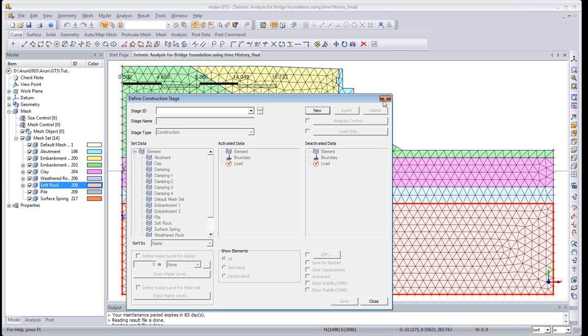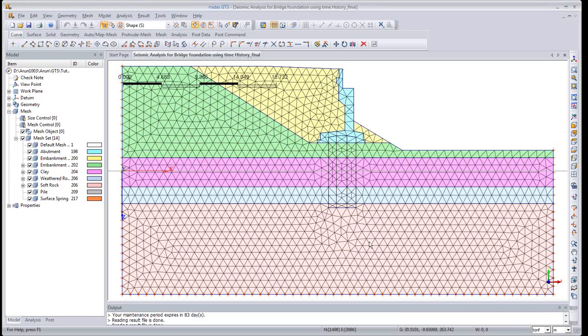So once you have generated the basic geometry, it's purely up to you to decide what type of analysis you would like to perform depending upon what you would like to achieve. So you need not change anything in the model once it is generated. All you need to do is just change the external factors like boundary conditions and loadings to cause different variations.